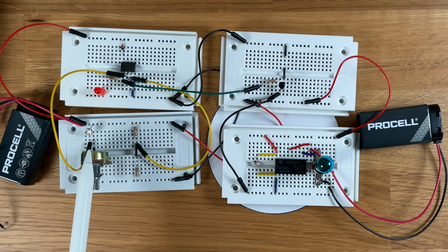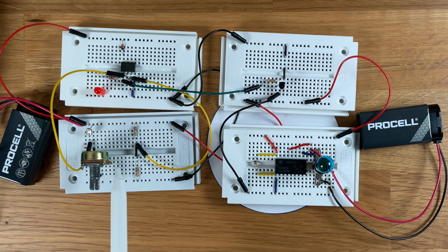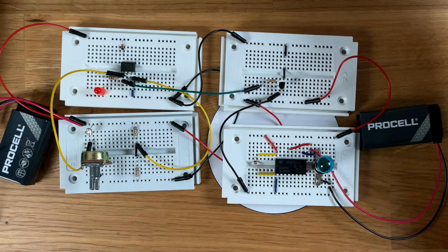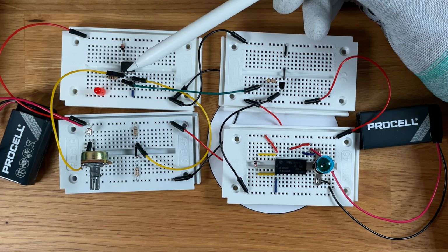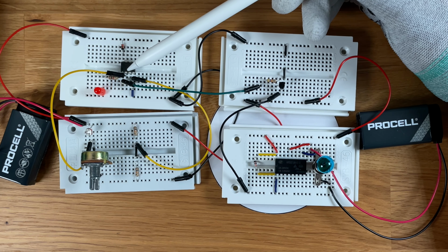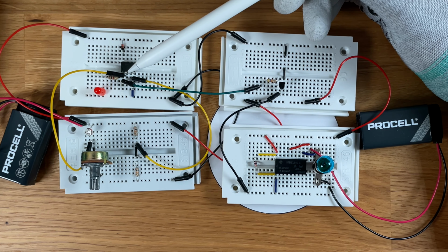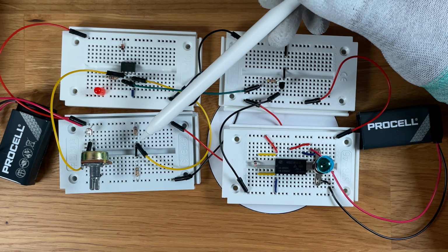And in an ideal situation where we have exactly balanced the Wheatstone bridge, which this is, this measurement bridge, to have exactly 0 volts across it, then we can use the operational amplifier here, which is used as a comparator up here to react to this voltage difference between these 2 points.